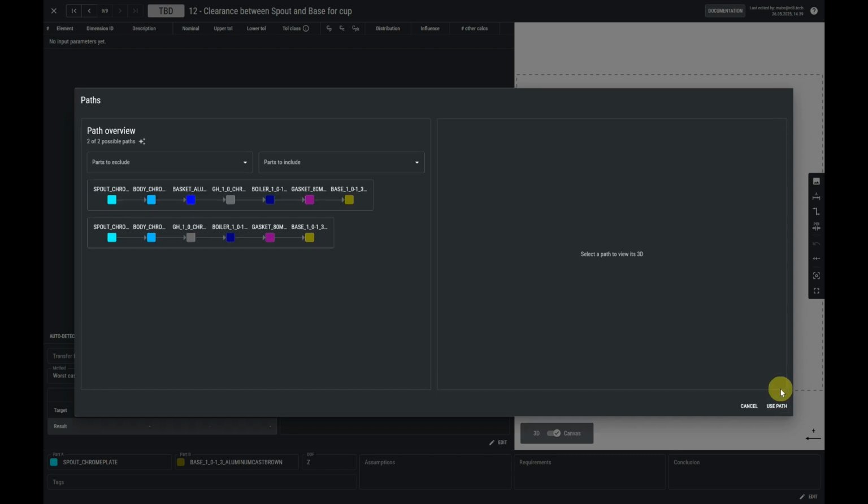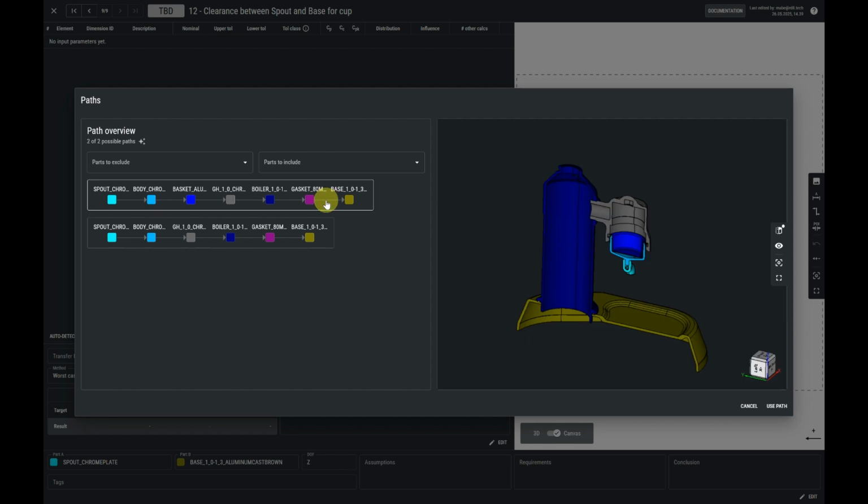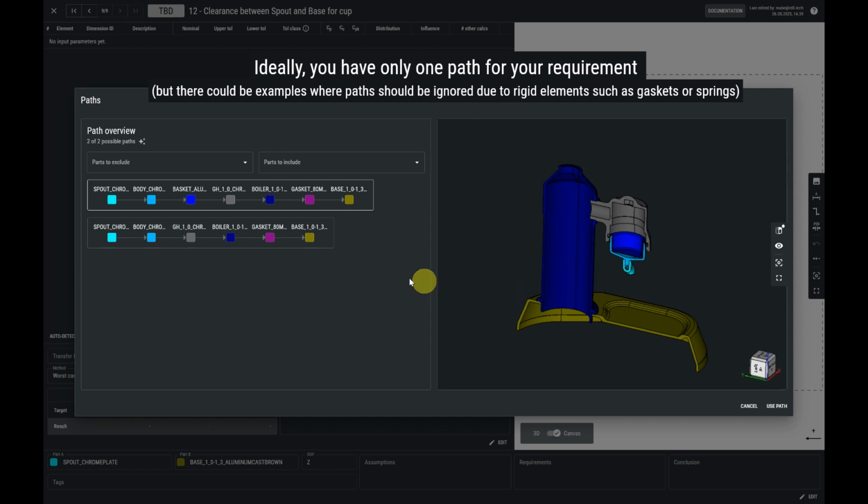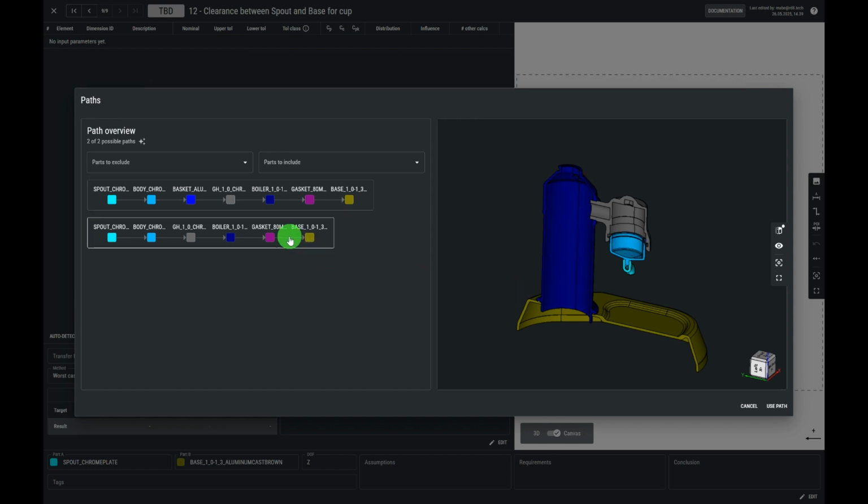This is a valuable help, since the paths detected are not based on your assembly mates or any other idealized information. We find the paths based on the actual geometry in your model. So if you accidentally created a design that could have multiple force or tolerance paths competing to create your function, this will show up here. For this tutorial, I will not do anything about my unwanted path and focus on completing my needed calculation.